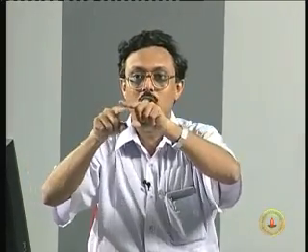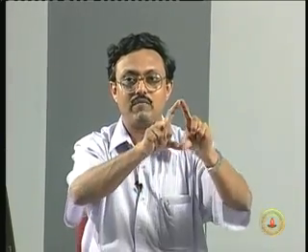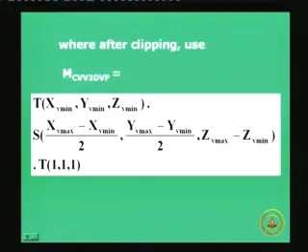If this is the screen which you are seeing right now, you will say, okay, I don't want to see all the text in the entire screen, I would like to select a small portion here or maybe some portion here. So that is what a 2D viewport is. I will say I want my display on this particular graphics package to be positioned here or somewhere here. That is what we call a viewport, and what you may need to do is take the 2D device coordinates which will be generated with respect to the whole setup. You need to scale it down and then translate it and position it in the viewport which you demand or the user asks. So you need to map it into a 2-dimensional viewport.